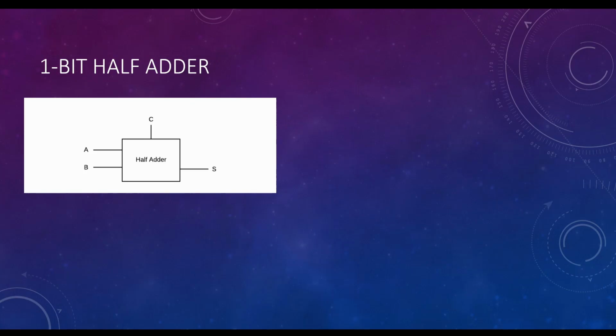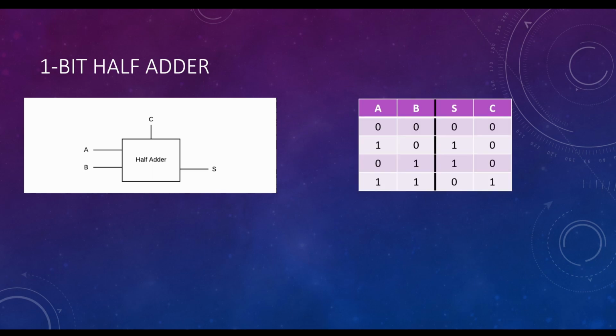What we just did is called a half adder. A half adder has 2 bits as input. It has 1 output that is the summary and 1 output which is the carry. And this is the truth table for a half adder, and you can see that it matches exactly what we did on the whiteboard. This is a canonical equation that expresses the same table.